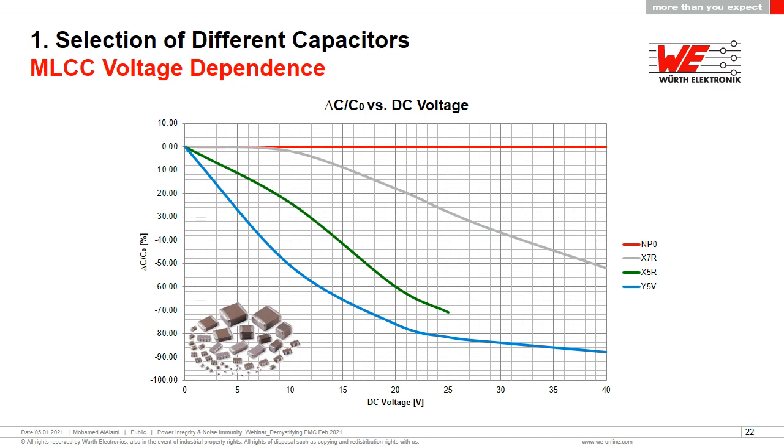So where is the issue with using MLCCs? They're fantastic. You said to us it's fairly low ESR, so why do I need to go across to polymers? Everything has its place in a power supply, or in general in electronics design, I should say. And I'm not saying that MLCCs do not have a place. They absolutely do. They're fantastic components. However, they will also have limitations.